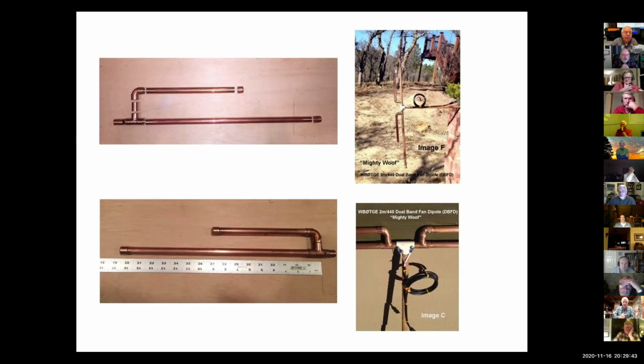If you're gonna build an antenna like this, you want to cut the pieces to the lengths that are kind of given, and then do an SWR check on it before you solder it together. You want to get the lowest SWR that you can when you're building the antenna. As you're trimming an antenna back and forth, you can build a 2-meter J-pole antenna. It would be a section that looks just like that upper left-hand corner, but with given dimensions, and you can find these dimensions on the internet.